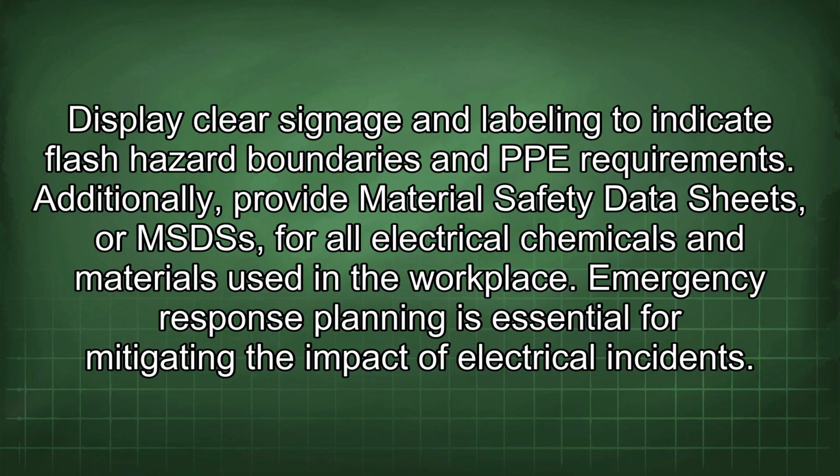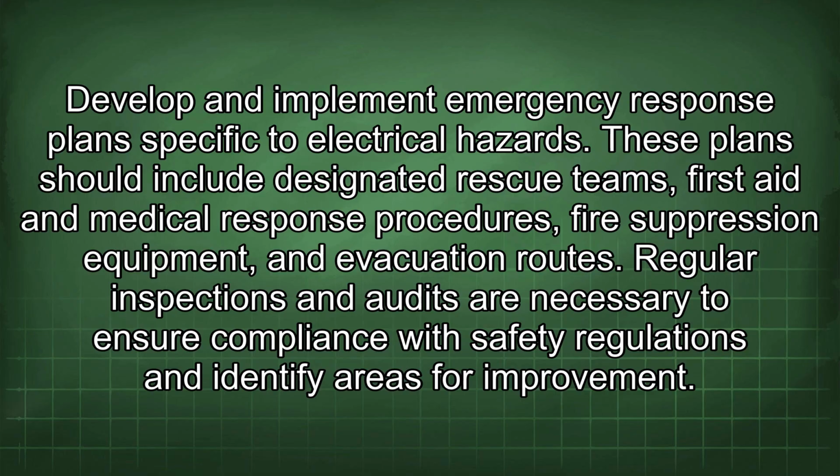Emergency response planning is essential for mitigating the impact of electrical incidents. Develop and implement emergency response plans specific to electrical hazards. These plans should include designated rescue teams, first aid and medical response procedures, fire suppression equipment, and evacuation routes.